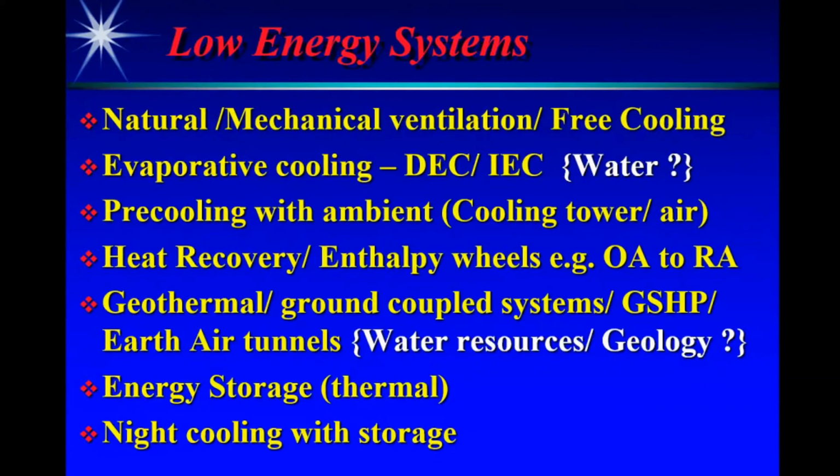The second technology which has been extensively used in countries like India is evaporative cooling. Direct evaporative cooling has been used, desert coolers as we call them, for decades with very good success. The only concern which people are now raising about these systems is you need water for their operation. So water is also becoming a scarce quantity other than energy, and one has to look at the trade-off which is there. The other thing we have to keep in mind is evaporative cooling systems cannot be used in humid climates, and that is their limitation, and they cannot be used for removing the moisture from air if the latent loads are high in the conditioned space.